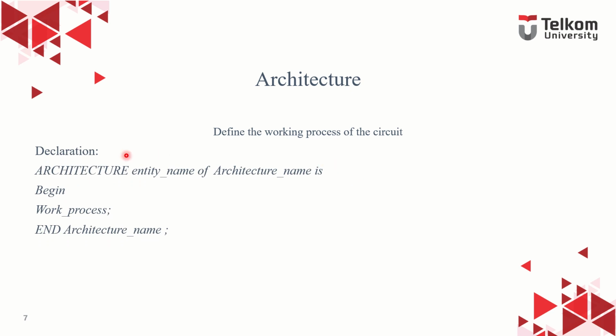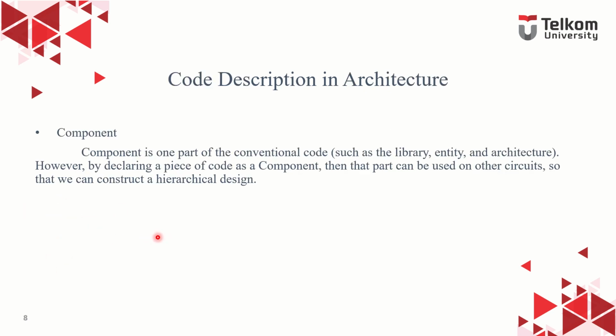The declaration is like this: architecture, architecture name of entity name is begin. And in here, you will define the process and end architecture name.